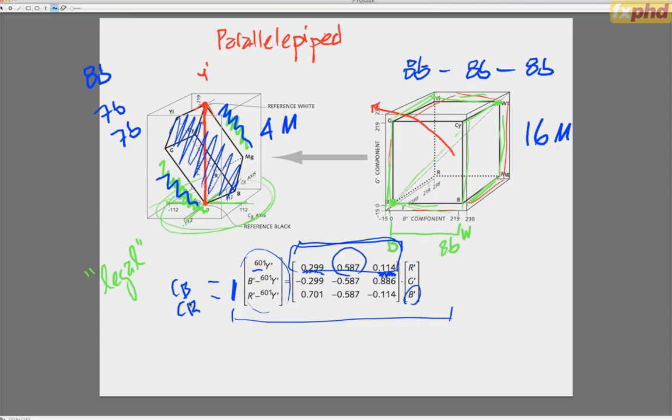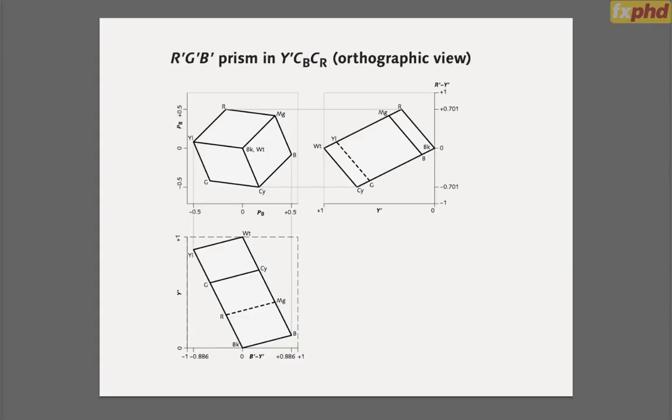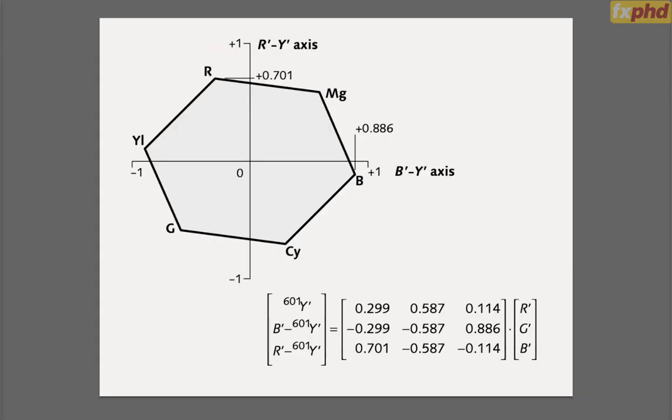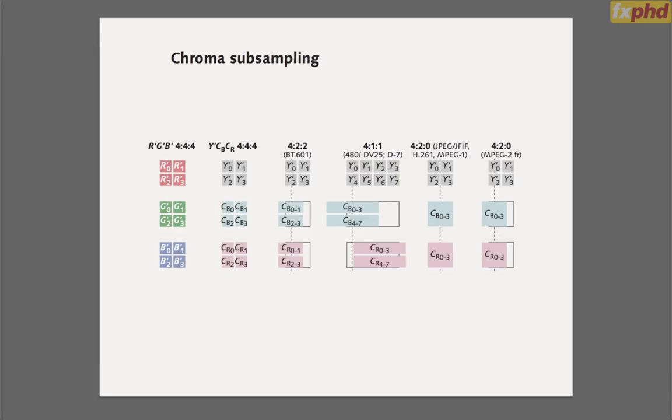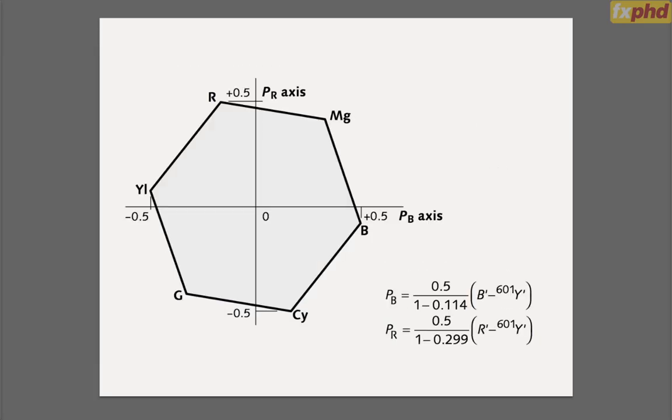And I'll very quickly show you the scaling equations. This is basic theoretical color space. The chroma components go to ±1. That's not convenient. So we simply scale the two chroma coordinates. That's all that's going on here. We go into either PBPR space, which is JPEG color space, actually. JPEG does all of this arithmetic because they get a 2-to-1 data compression for free. So this scheme is the front end of virtually all JPEG compressed images.